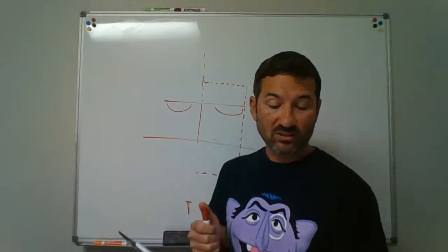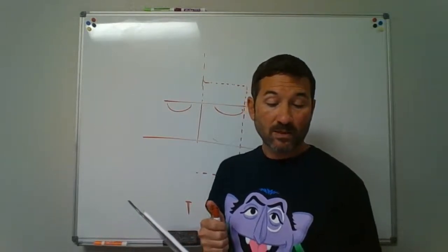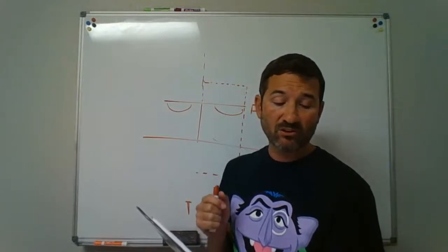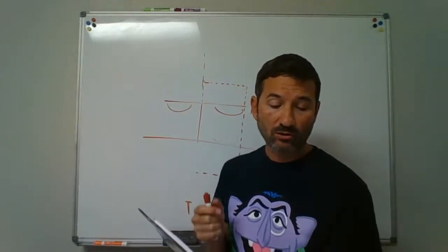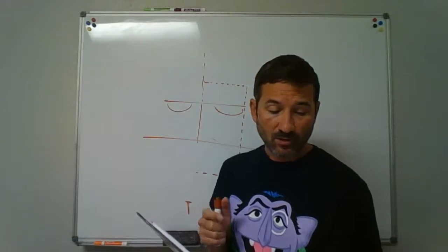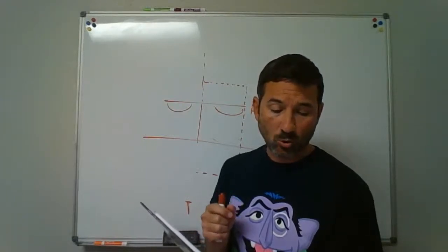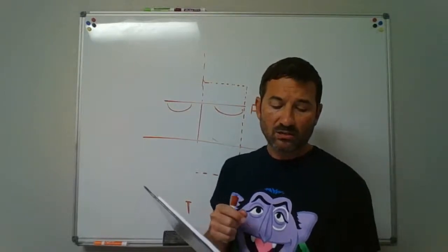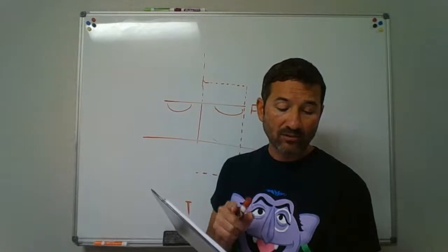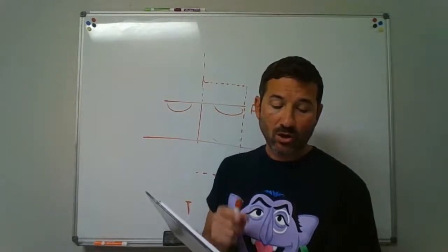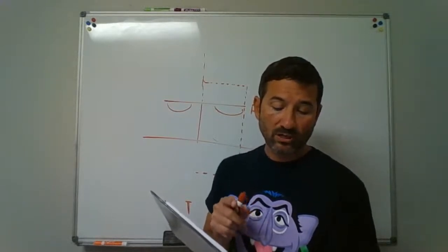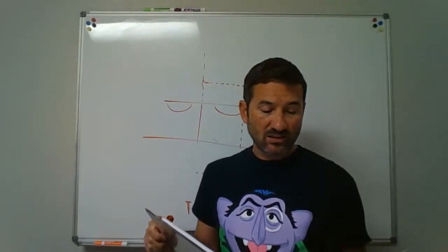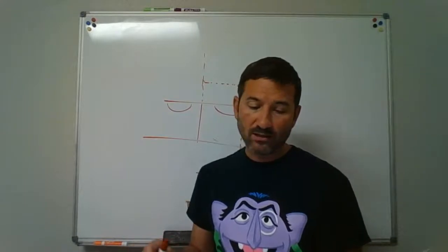Vent pipe sizing, section 906 on page 76. The minimum required diameter of stack vents and vent stacks shall be determined from the developed length and the total of drainage fixture units connected thereto in accordance with table 906.1. But in no case shall the diameter be less than 1/2 of the diameter of the drain served or less than 1 1/4 inches. Okay, so it does give you 906.1.